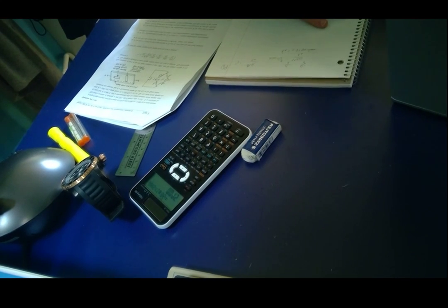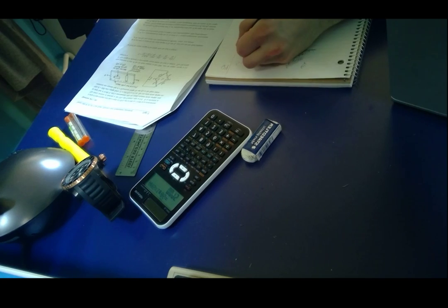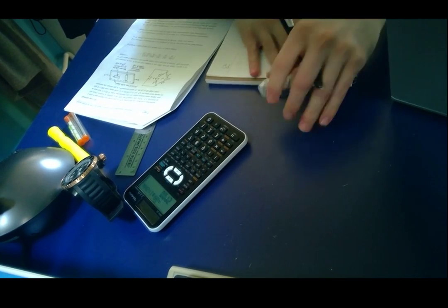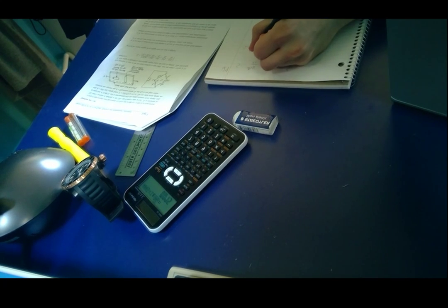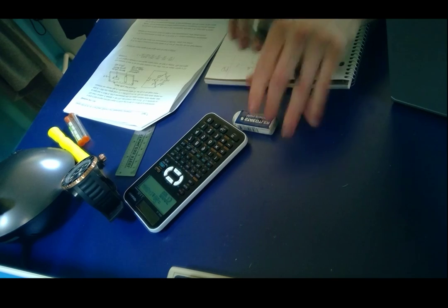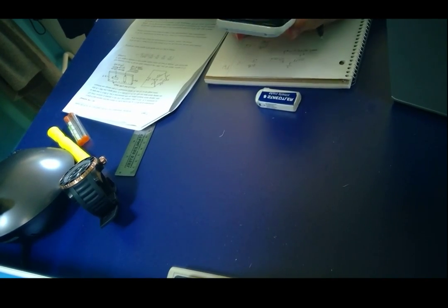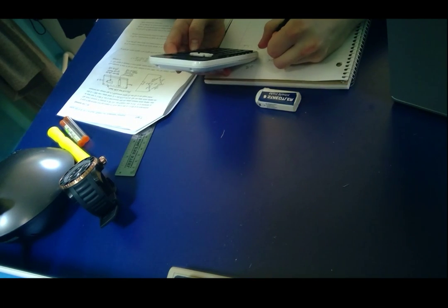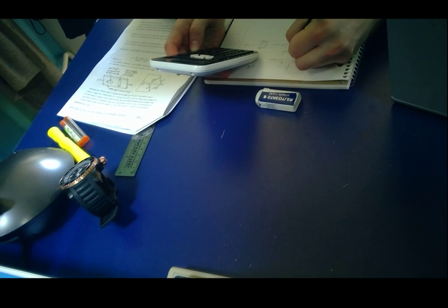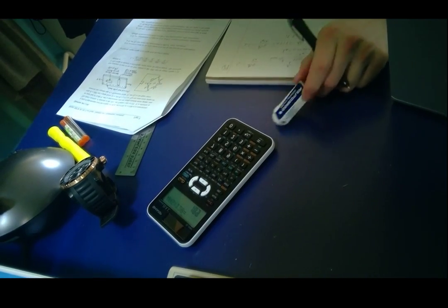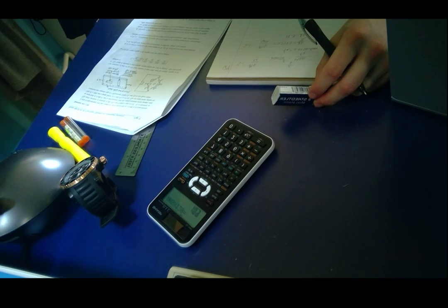All right. Now we know this, we know the S, so we know that it's 2.1. I'm going to erase this. 2.1 is equal to dR over R over the axial strain, 0.075. Multiply this by 2.1. 0.1575 is equal to dR over R. Now we know that R is 120, so times 120 gives us 18.9 is equal to dR. That's a lot. 18.9 is equal to dR. I actually can't believe that.